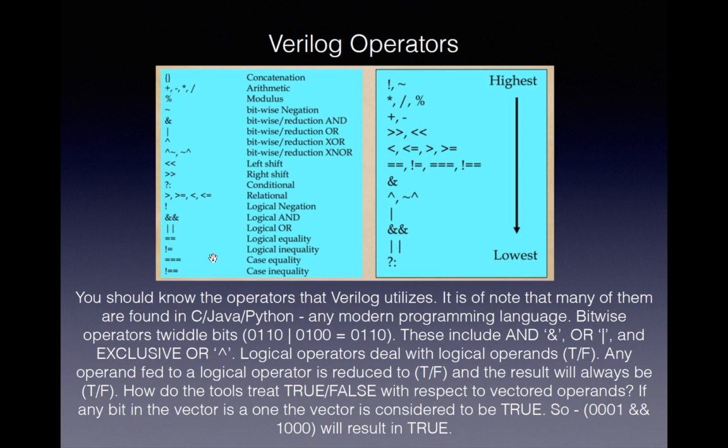The reduction operators are referred to as unary operators. There's one operand, and a unary OR bit reduction ORs all the bits together, producing a 1-bit result, or all the bits 1. So I was somewhat disappointed here, but by putting together this presentation, I'm hoping you take the time to walk through and understand it.